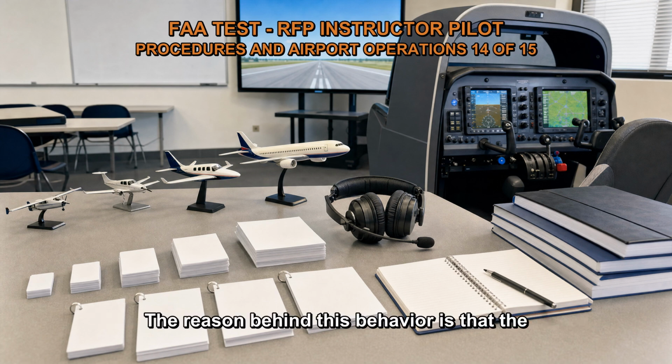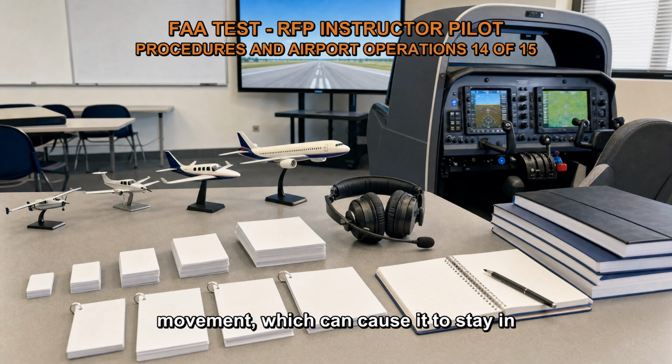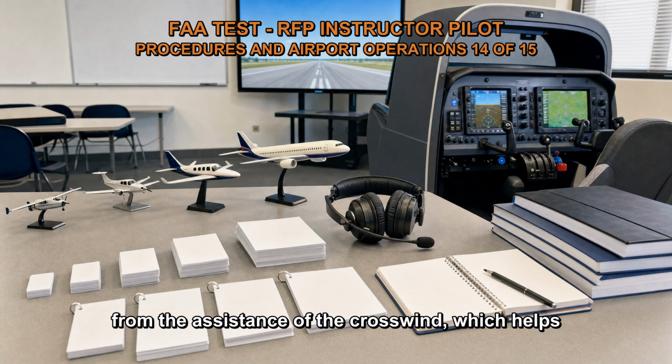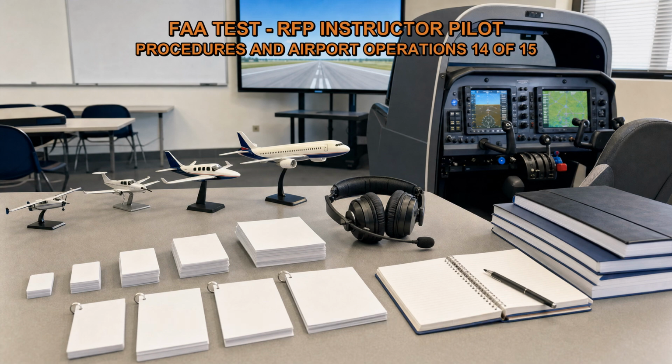The reason behind this behavior is that the upwind vortex experiences the crosswind directly opposing its movement, which can cause it to stay in proximity to the runway and take longer to disperse. On the other hand, the downwind vortex benefits from the assistance of the crosswind, which helps it move away from the runway more efficiently.